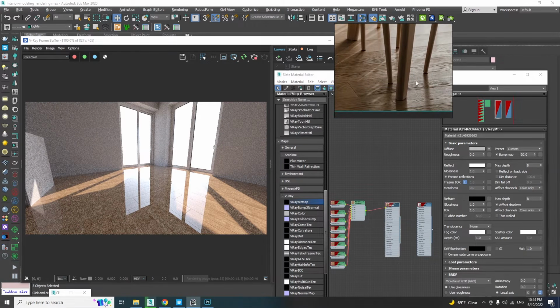As you can see in this picture, the surface has different glossiness in different areas. Where it has this matte finish look, we should use a lower glossiness value, and where it looks glossier, we have to use higher values. So when we have this type of situation, we have to use a map for our glossiness, and in this case, we should use the textures that we already have.